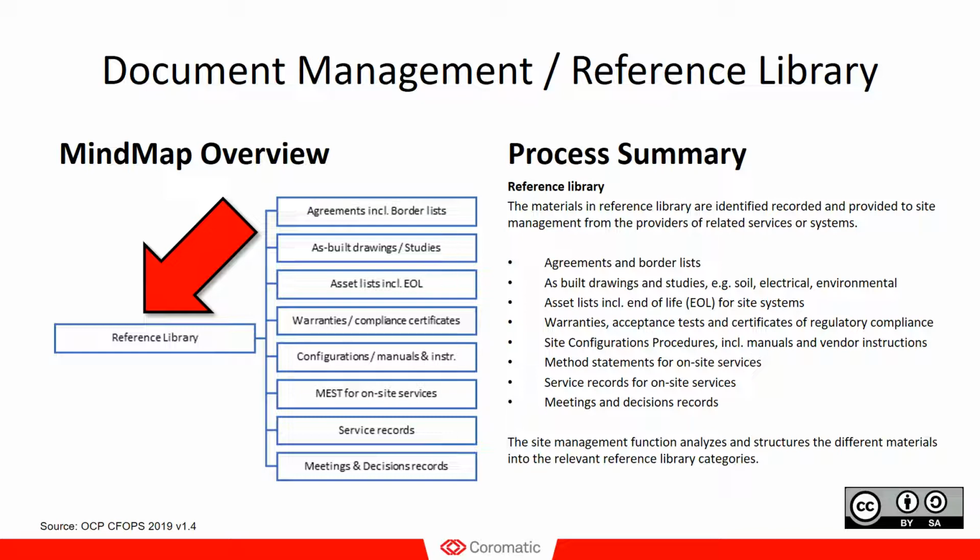This means that there will be changes in the live environment, and that needs to be reflected also in the documentation, which means the as-built drawings, for example, need to be updated if the power distribution is changed or developed. So do we have the latest single line diagrams in place where we can find them? That is sort of the key question for this one as an example.